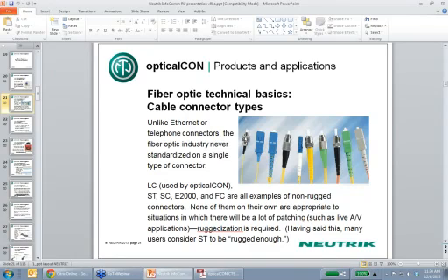This connector here, ST, some people consider to be a rugged connector. It's not technically a rugged connector. It's used a lot in broadcast. It's got some metal, so it's sort of rugged enough. But you see it still has all this exposure of this ferrule. So just know that sometimes you'll see a lot of ST used in broadcast. In Europe, it's no longer used. In the U.S., we still use it. Our belief is that the ST connector will disappear from rugged broadcast types of use in the future. It does have the advantage of being metal, where these other ones tend to be plastic.